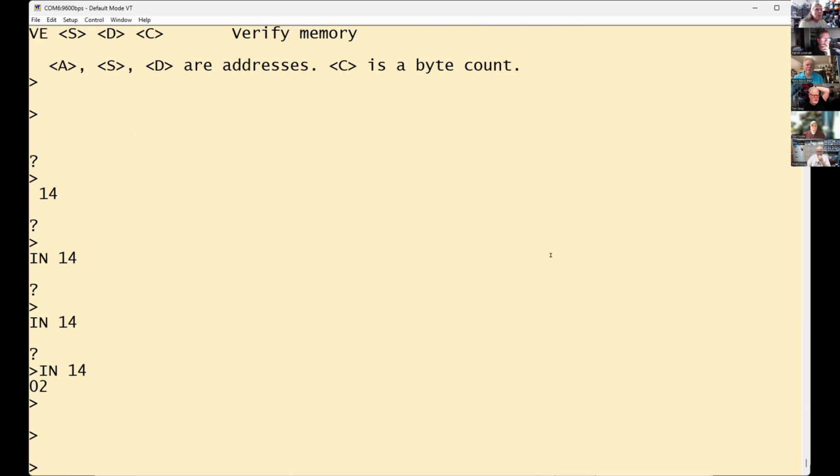So when I'm testing ports, I use IN and OUT all the time, and then a second system that can see the other end. Or I'll put two consoles at the same time, one on one and one on the other. I can connect a serial cable to that port instead of the modem. Yeah, and then just send it a character, and then you can run it to another terminal. That's the way I test a lot of this stuff because you take more of the hardware out of the situation. Less variables, always good.